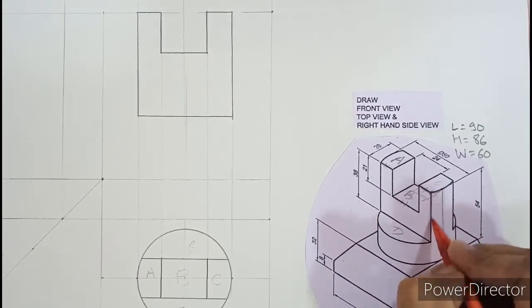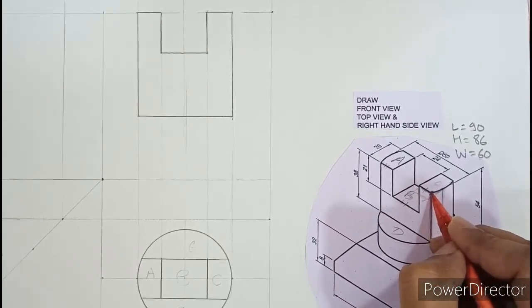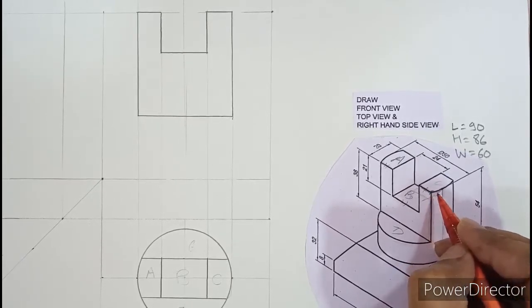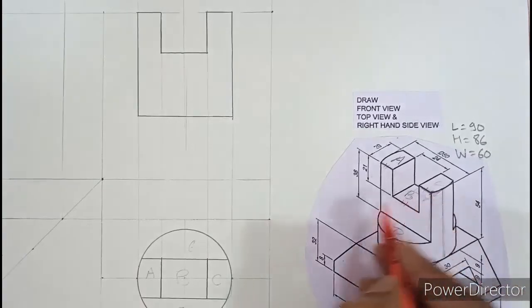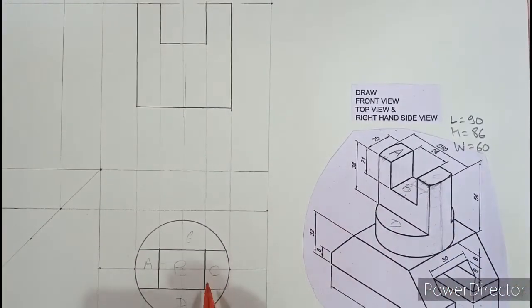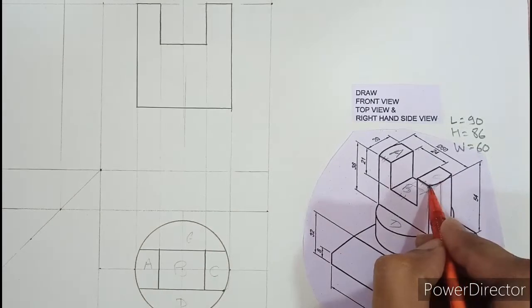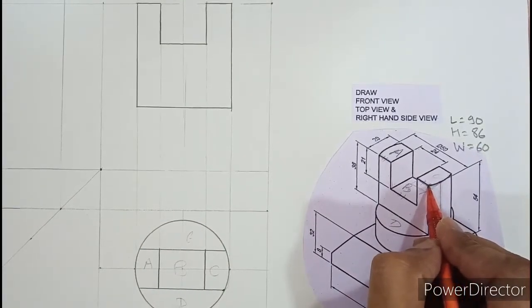How will you locate? So let us ask the top view. If you look in the top view, this edge is seen as a point, isn't it? So try to identify or locate this point in the top view. If you compare this diagram in the top view, observe thoroughly, that point is this one. Try to understand this point and this are one and the same. So if you can project this point, you will get an edge.